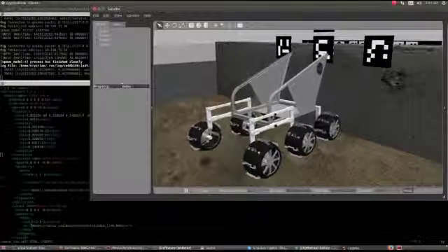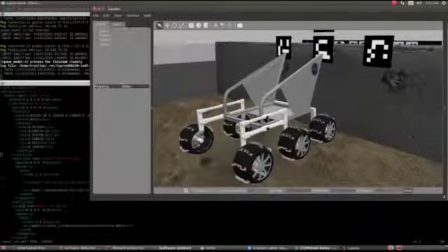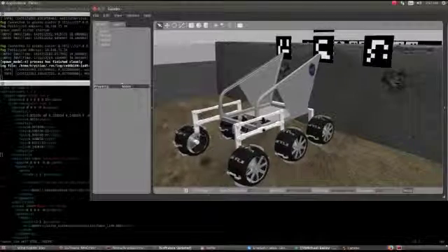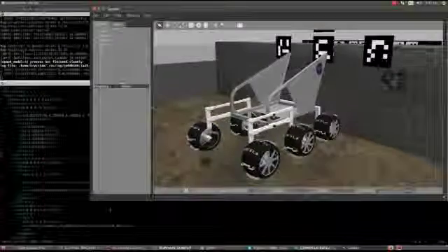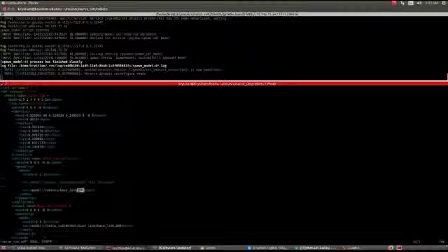You'll notice here that the visual portion for the base link is going to have a different file extension rather than STL, which we use for the collision portion of the linkage for the base link. It's going to be the DAE extension, which is the exported mesh from 3D Studio Max. So that's just for visual purposes. This is what goes in the visual tag here.